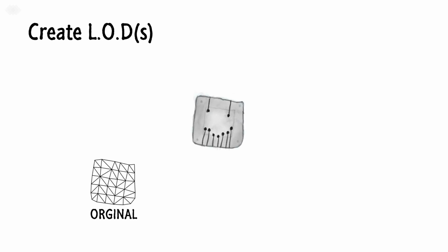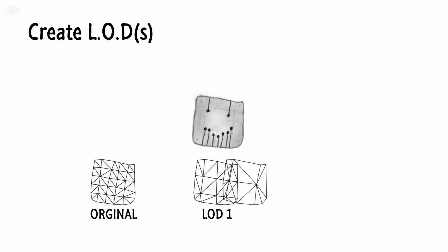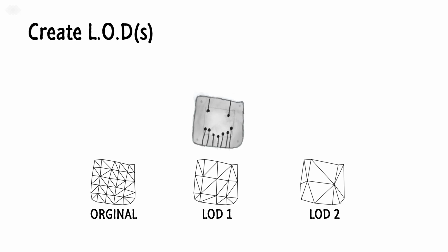LODs. LOD or LODs are versions of your mesh with fewer triangles and fewer small triangles than the version before. Each LOD step, and only that step, is displayed at a specific distance from the camera. This allows you to have details up close and also have a version far away with details removed. This is in order to get good performance. Let's look at a game example.